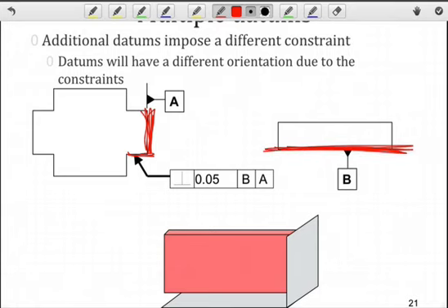And then, as you know, we're going to bring in a surface plate here representing A to establish that datum reference frame, and we should probably show that feature there and here. And so now this has to be maintained perpendicular to B, then A. So we're adding an additional constraint, and we're adding a different type of impact. We're concerned about the relationship to the bottom of the plate as well. Again, the size of the tolerance zone is the same, the shape is the same, we've just changed the constraint.